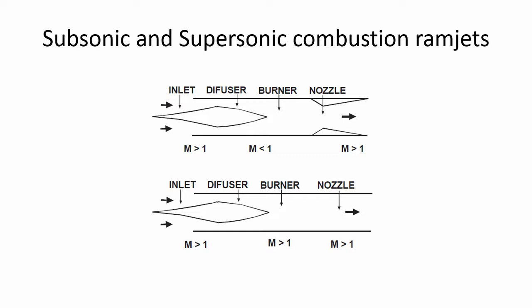Now, scramjets, which are essentially supersonic combustion ramjets, and normal ramjets work on a similar principle, that is, they do not have a compressor or any rotating machinery to compress the air. In this case the incoming air is compressed by the ramming action of the air into the engine, and that ramming action is created by ramming the supersonic air into a converging flow path, that is how the inlet is designed, as you see here.